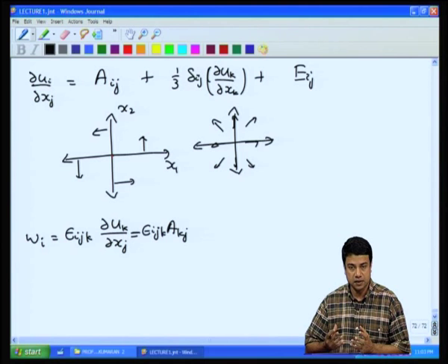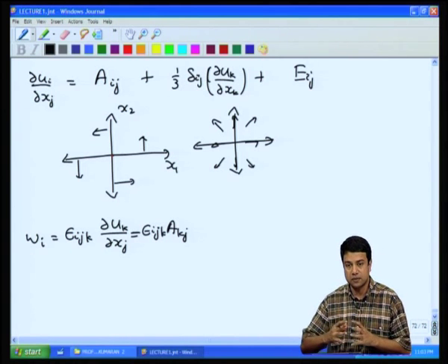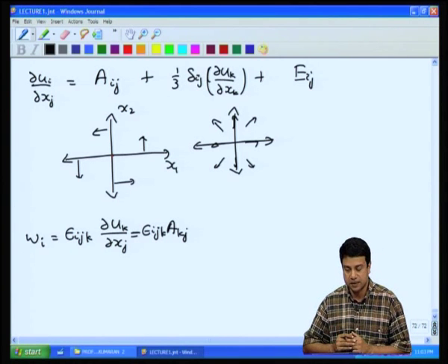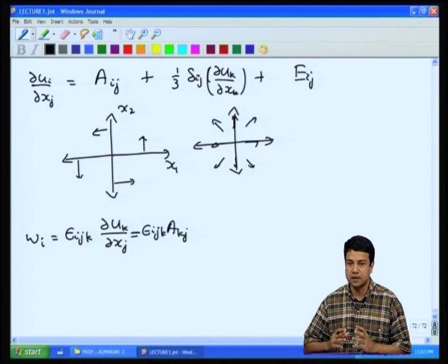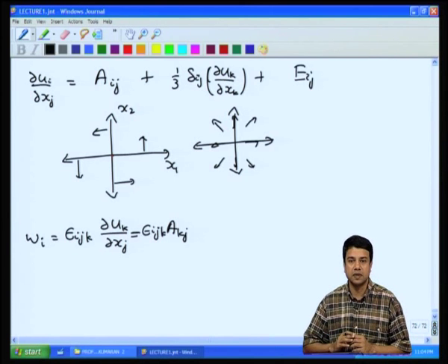As I said, the volume has to increase for the divergence to be non-zero, because the divergence of velocity integrated over a volume is equal to the integral of u dot n over the surface. So, if that is non-zero, that means there is net fluid coming out of that surface. Okay. So, there has to be a source, or the density has to decrease. Unless the density is remaining a constant and there is no source of fluid, this part will be identically equal to 0.